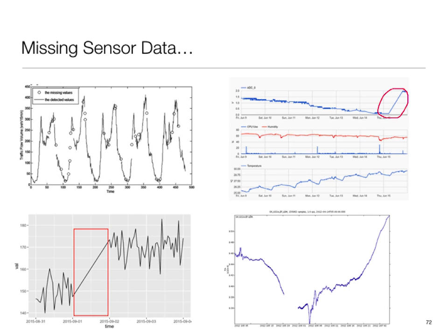So you have interpolation from past and future, and you have imputation, which is from the other channels. Collectively, by applying all of these things, you can at least have a system that is more graceful in its behavior. Again, in almost any sensing system you would see these outages very commonly, and this software complexity comes in and bites you.